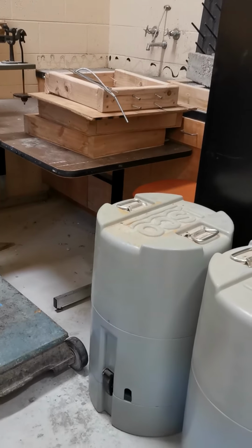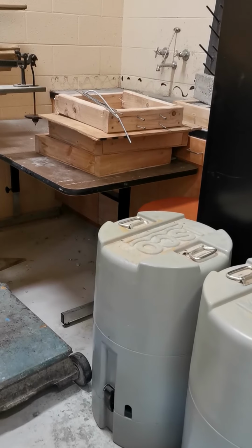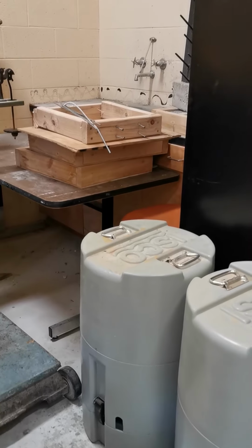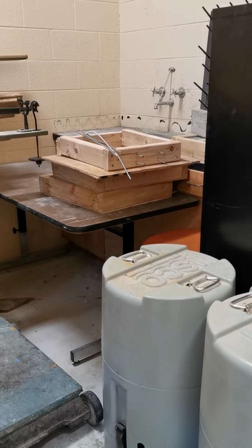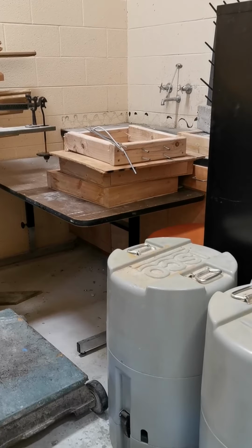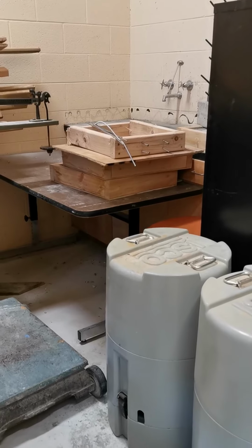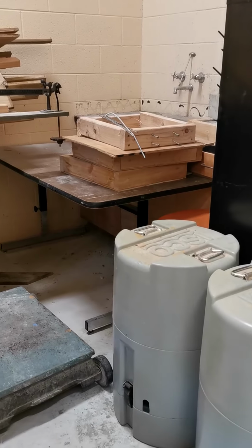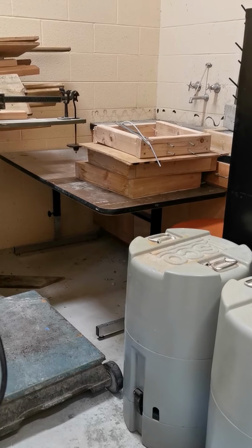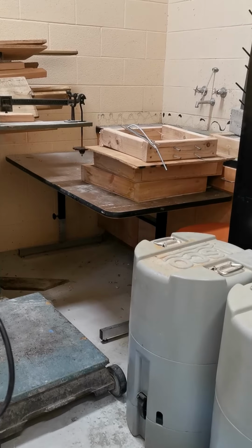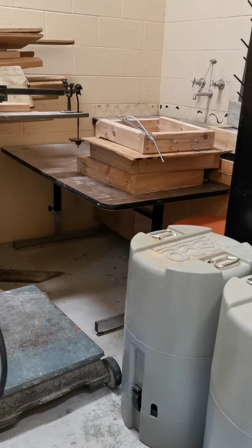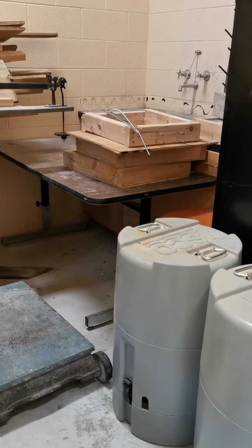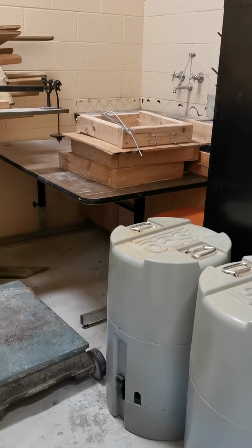So then the reinforced concrete beam is left to cure in the molds, and after 28 days the students come back to test this. Meanwhile, they also do a simulation of the reinforced concrete beam using the concrete damaged plasticity material model for concrete and an elastic perfectly plastic model for the steel.